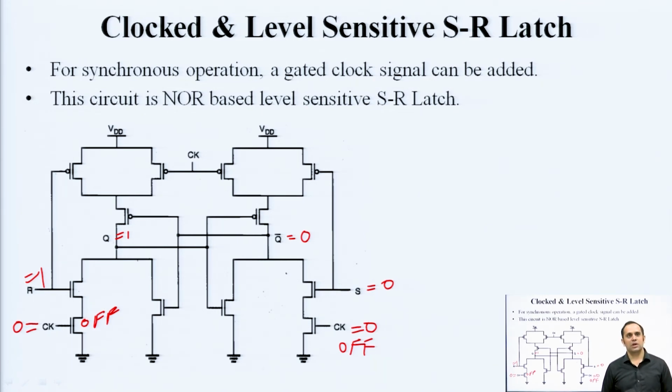So any kind of latching operation requires some kind of a trigger, which is generally the level at enable or clock, and that basically decides whether the output will be updated, or the output will be latched only, or the previously latched data will remain. This is how level sensitive latching works.